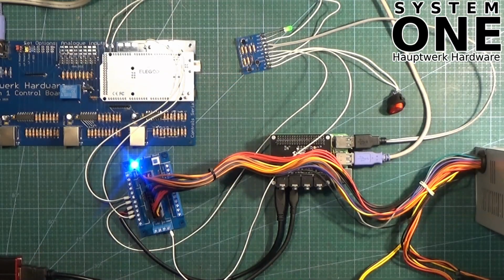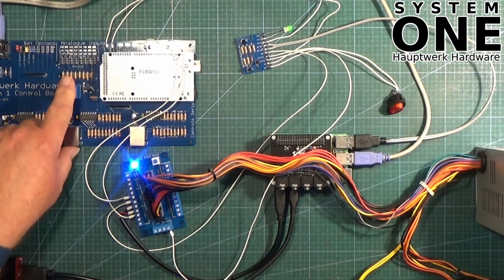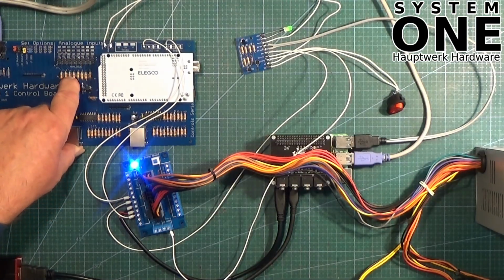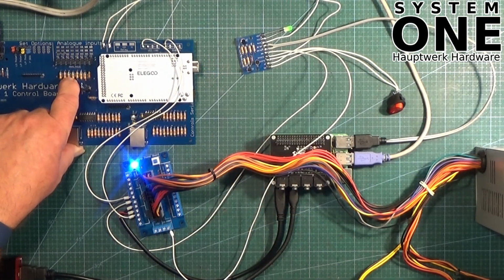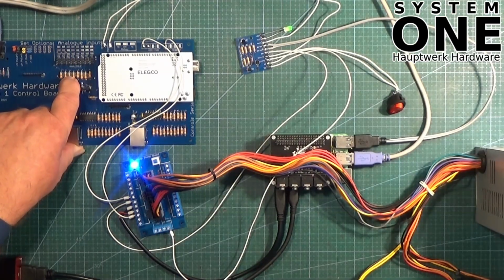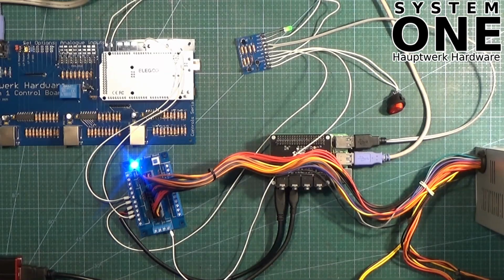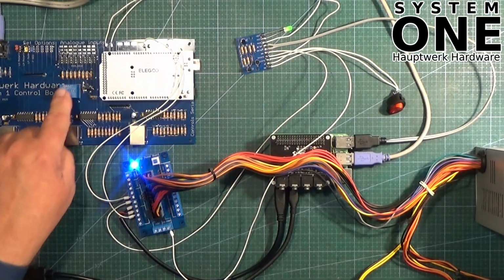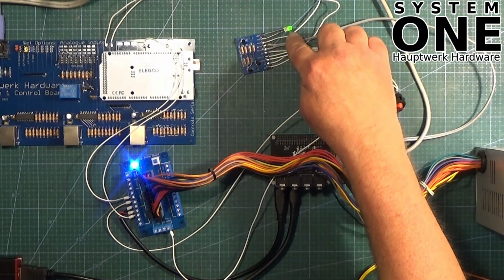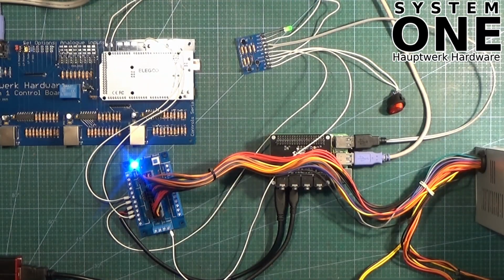When the LED went green, I don't know if you noticed, there was a tick, and that was this relay switching over. And this relay is connected to these three solder pads at the back. There's a common, a normally open and a normally closed. They're just dry contacts, meaning they don't have any voltages or anything else on them. And we can use those for amplifier muting or pretty much anything else that you want to control once this is booted up. So when it's ready to play, the relay switches over. You can use that for whatever you want.